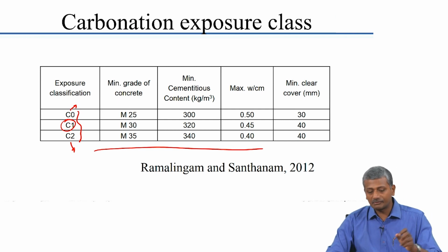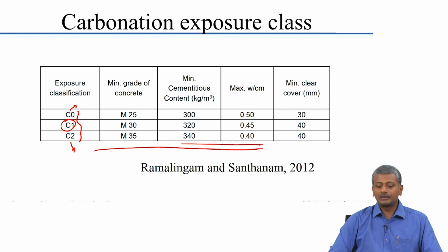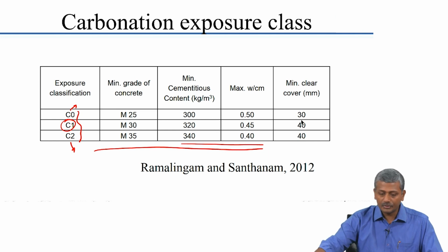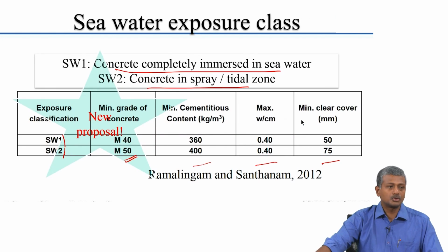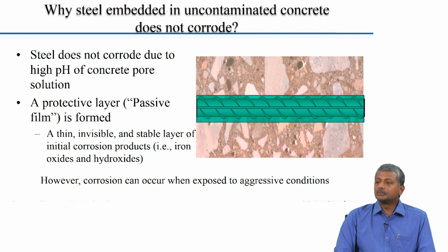Okay. So, these are different service environments. You can see that the requirement for durability in terms of carbonation exposure is not that stringent as it is in terms of seawater exposure. The water cement ratio required in seawater exposure is usually much lower than in the case of carbonation exposure. Okay, so coming back to corrosion.